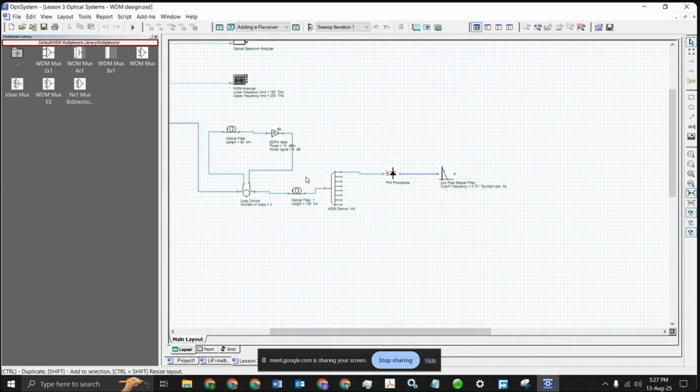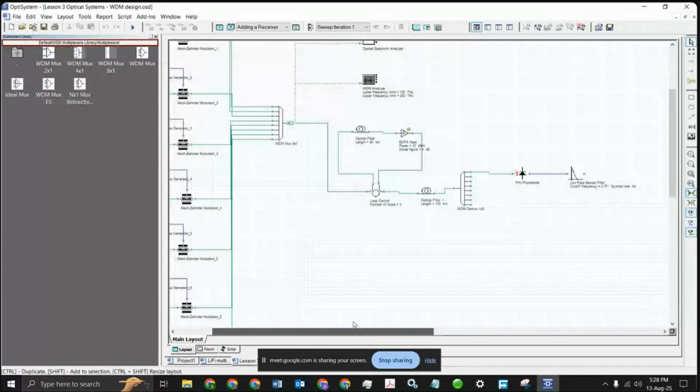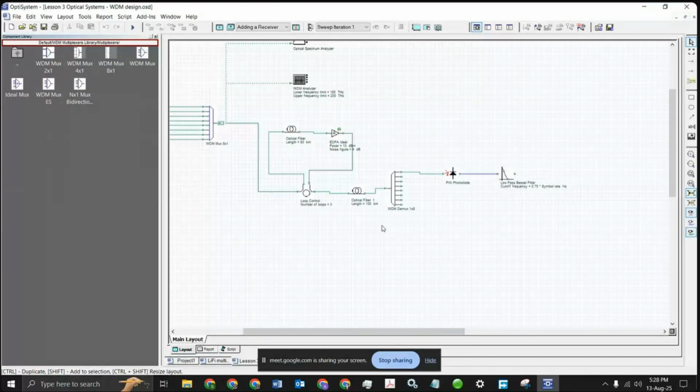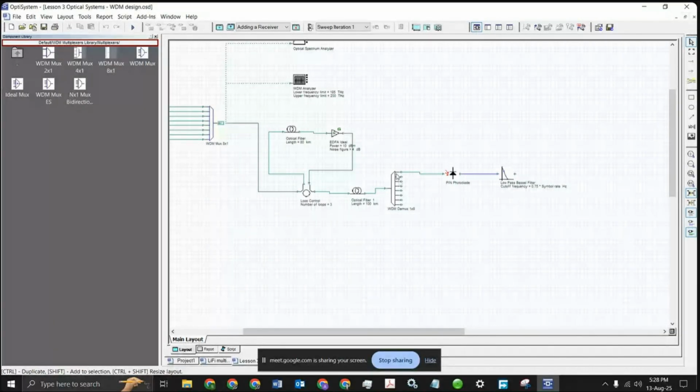And once we are sure that, okay, it is fine, we have sufficient length, then you can separate this with a WDM demux. So we are demultiplexing it, detaching, or you can say bifurcating the various wavelengths. That is the only reason the name of this application is wavelength division multiplexing. So you are utilizing this for dividing the various wavelengths into various application segments and distributing each application wherever it is required.